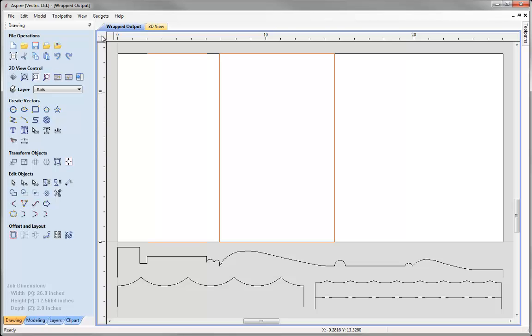So now there's one more vector we'll need to create the swept shape that we want for this section, and that's something where we're going to extract it from the original profile we've got here. We're going to use this to give us the depth of our octagon. Now because we're going to use this to give us the depth, on these shapes here I won't need these vertical edges. So I'm actually going to select those, hit N on the keyboard, hover over that span there and hit D to delete it, hover over this span here and hit D to delete that. I'm going to select this cross section, hit D to delete that and D to delete that span there. So these are just going to give me the octagonal shape. I'm going to use this bulge and sweep that along to give me the depth.